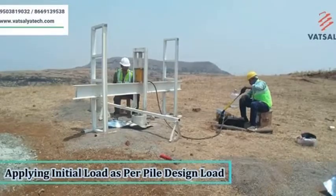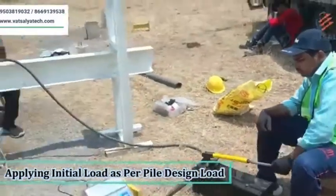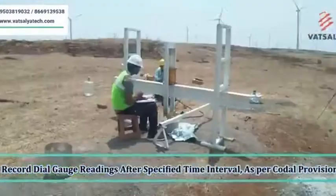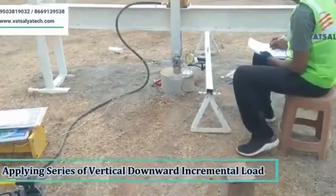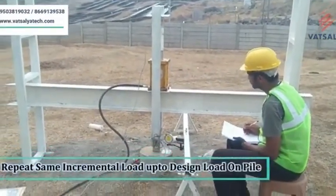The load used for this test is usually applied incrementally. That is, if you want to use a 100 kN load, for example, you will start from 0 kN to 20 kN to 50 kN to 80 kN, then to 100 kN, or any way you wish to increase the load. Just do it incrementally.